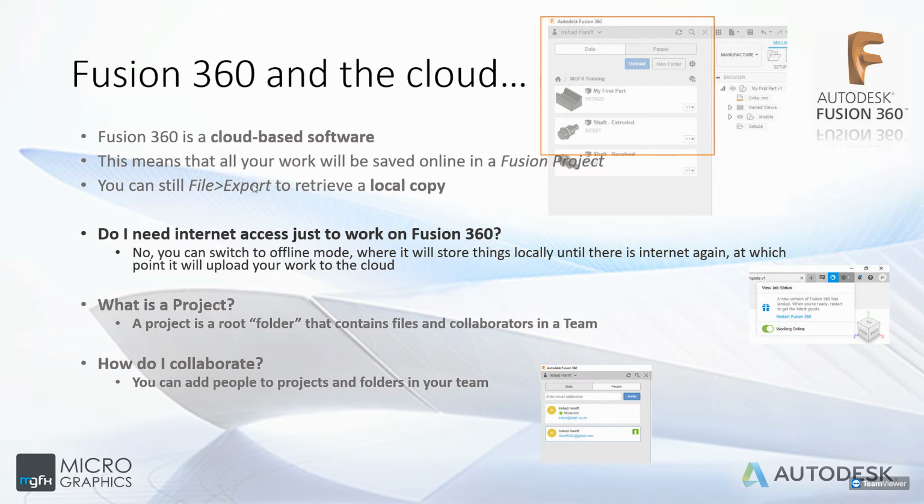Right? So does that mean I need internet access just to work in Fusion 360? The short answer is just no. You do have a little switch here, and it looks like this. If you look on the right, the small image here, there's a little switch to tell Fusion that you're working offline, and it will still allow you to do everything that you need to, right?